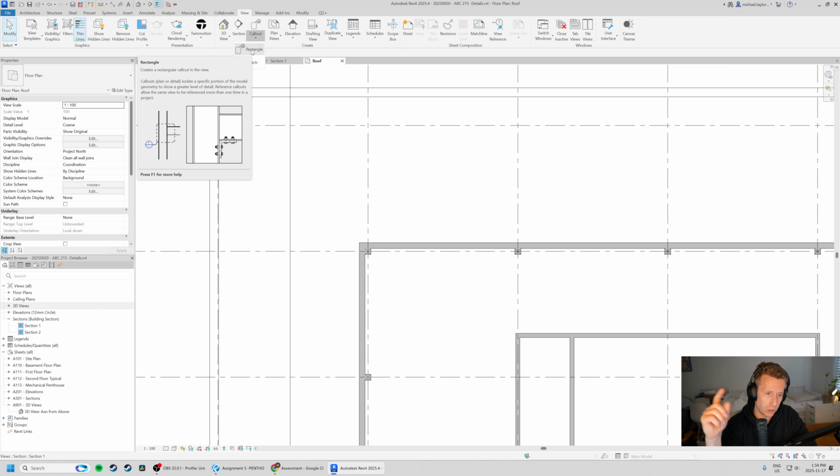So in AutoCAD, you used to have to go around your building and create all of these little bubbles. And then you go to your drawings and you figure out, okay, which reference was that bubble part of. For us, Revit automates this. This is rad. It solves a lot of what I would say were discrepancies between drawings. So what will happen is no matter what you do, if you update this in the model, if you update it in the sheet, your reference for this particular view will always be, for lack of a better word, correct. So I'll show you what I mean.